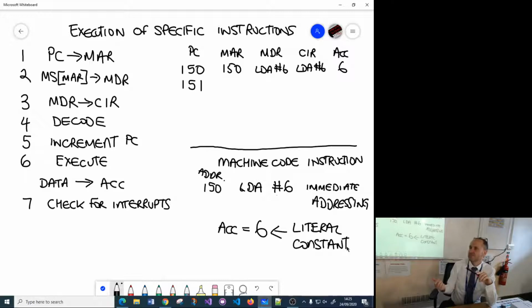Okay, in Motorola 68000, that uses a 16-bit instruction length, the immediate modes, there was only 4 bits. No, there was 5 bits, so you could have a number that was either minus 16 to 15. That's all you could have. But it was handy if you just needed to initialize values. You know, you wanted something to be 1, so you could use immediate addressing, and it was quick.